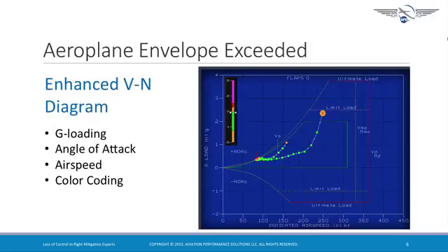This is an important envelope. This is where the instructor is going to be able to see how the airplane performed in a certain situation. In this particular situation, the airplane started at number 2. You can see the arrow progressing the airplane. Now it's going to start at a certain airspeed. Based on what we're looking at, I would say this is probably a nose-high airplane upset. We can't tell bank angle from this. That's another representation we'd have to look at. But we can see the airplane started at fairly high speed, and during the recovery, the airplane was unloaded, or G was reduced, and the airspeed decreased, which generally indicates a nose-high condition.